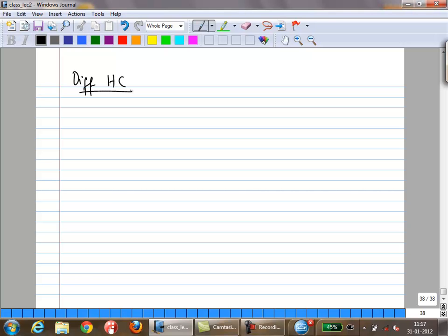So let's take the differential half circuit. You'd have R. I'm going to call this current ID over 2, VD over 2. What is this? IC times delta R over 2. This would be the differential mode half circuit.